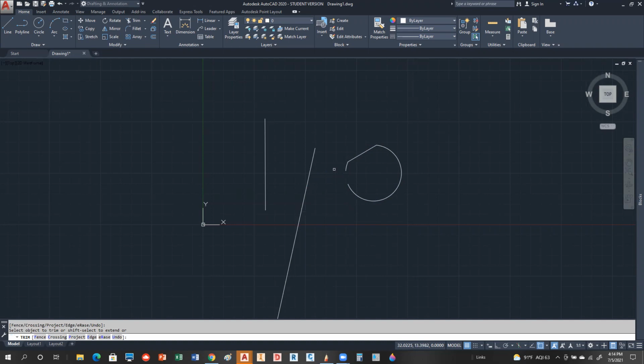And the same thing works if you are in the extend command and you hold the shift key down when you select objects, it'll trim. So it goes back and forth. And remember that this little guy, this edge mode guy, once he's turned on to extend or no extend, he stays on forever. So if you've turned it to no extend, it stays on, okay? And I think that's on by default. So if you're trying this, like I said, yours is probably set to no extend. So it's kind of nice to have it to this extend mode.